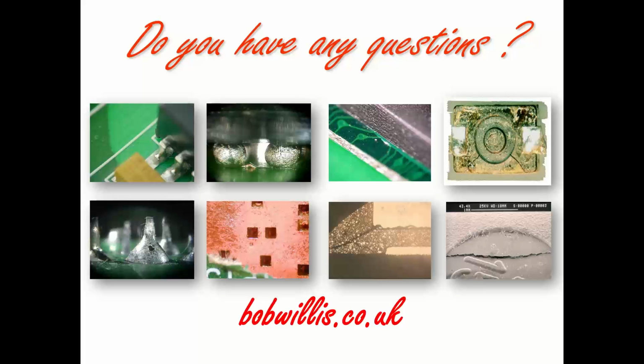Now, I worked for a connector manufacturer probably about 20 years ago, and we did a lot of work on this just to demonstrate their parts would not be affected. And this is with no baking whatsoever. So it's all about the plastic material, but sometimes it's about the molding material. Because if you've got a large cross-sectional area of plastic, as opposed to a thin area, you tend to see more cracking in some of the thinner areas where the molding material has built up stress during its flow in the mold. But again, if the material is compatible with these higher temperatures, 260 temperature, then you shouldn't really have a problem.